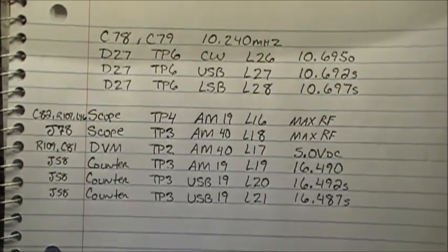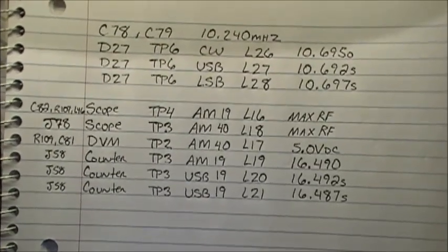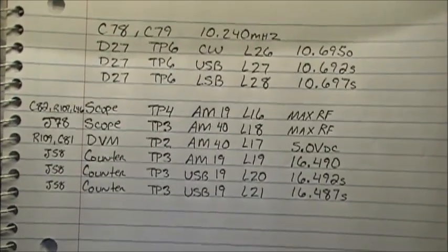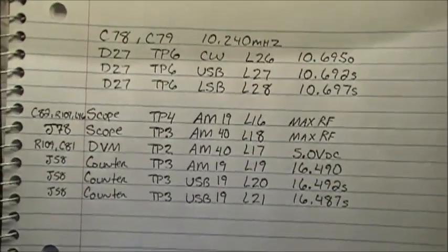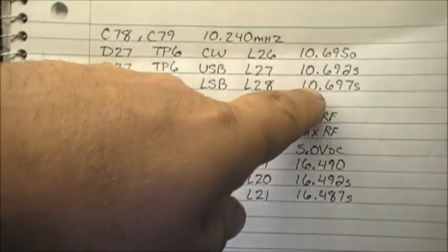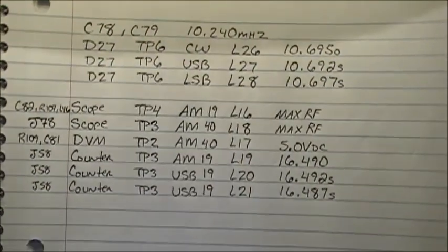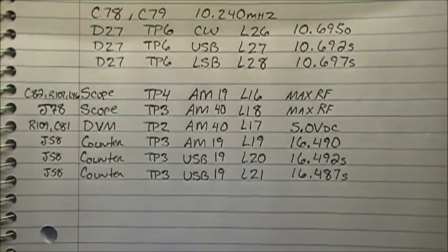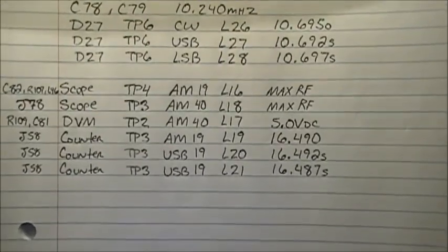The 10 to 40 is there, no problem. Then we have, I think it's a 14 megahertz crystal or 40 megahertz crystal, whatever it is. Anyway, that one is alive. But this little bugger here is dead. It's not oscillating in any way, shape, or form. It's doing jack. This crystal.